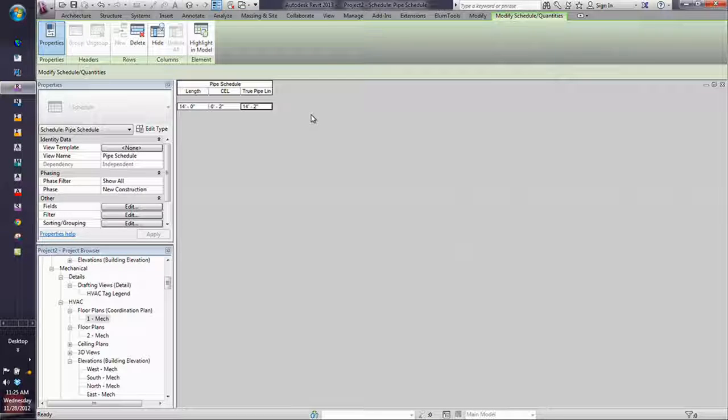What we did was we gave the architect a light masking family and let them go in and create that mask where they wanted the lights to be placed. It's nothing but lines. That's all it is. And then they drop in where they want a 2x2 or 2x4 fixture, mainly with the 2x4s. And so what we would do is we would let them put them in the architectural file and let that mask the grid. And then the electrical engineer would place the actual light. And that made it work a whole lot better.